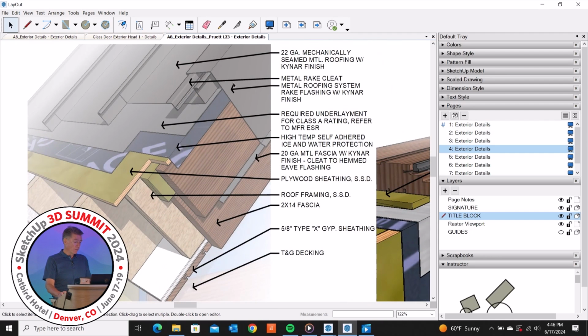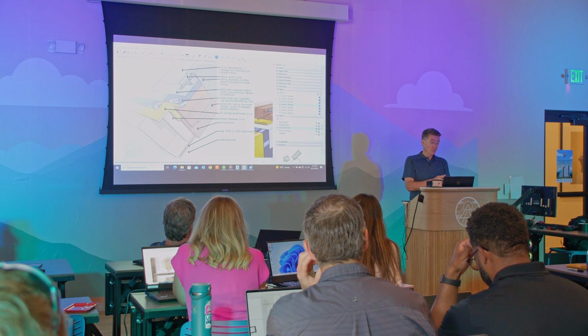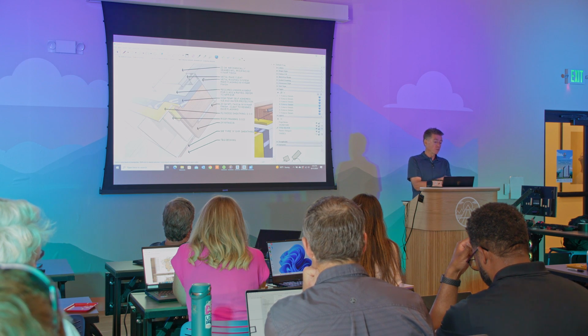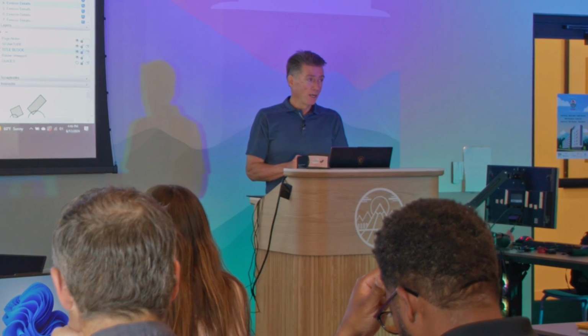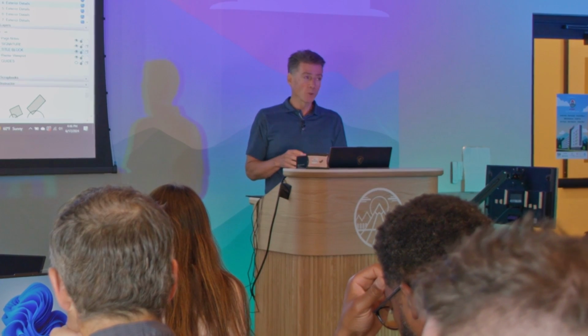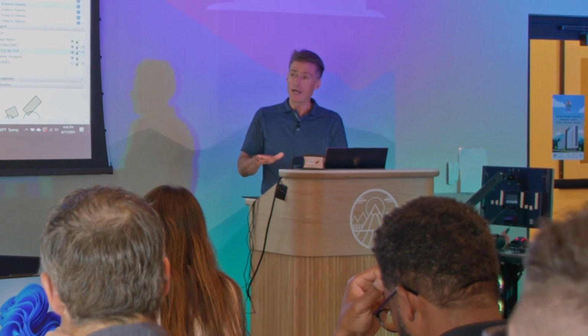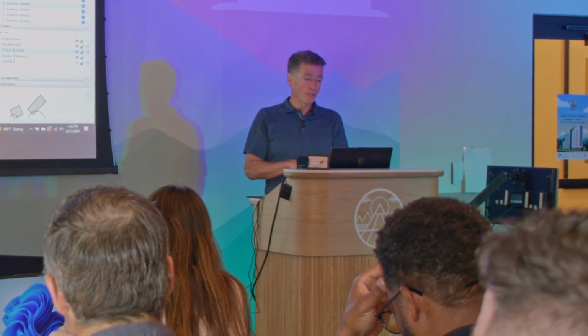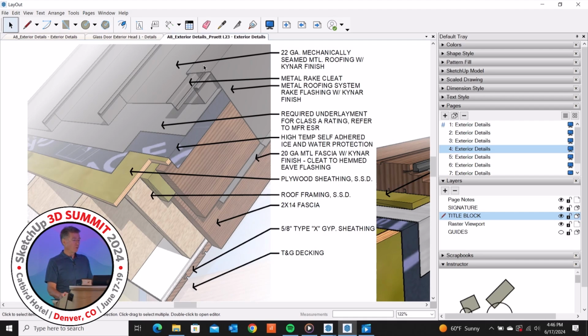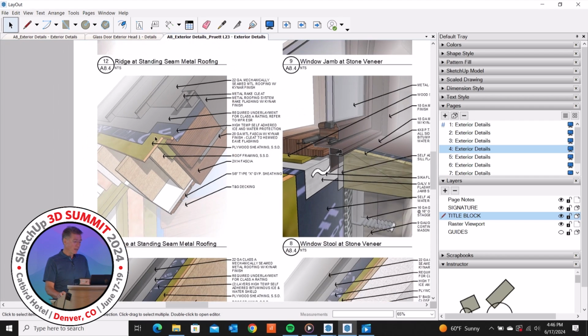And again, the key on this, and I always caution folks, is don't just randomly do details, but use manufacturer's details. And this is a classic example of, I get so many contractors that don't install the rake flashing piece that comes from the manufacturer. It's a dedicated piece or multi-piece edge that comes with the warranty, and 9 times out of 10 they go flat to the edge, and that doesn't work. Lay it on top of a standard edge flash. I think I have 1 job where they did it correctly, and I don't have much say in it.